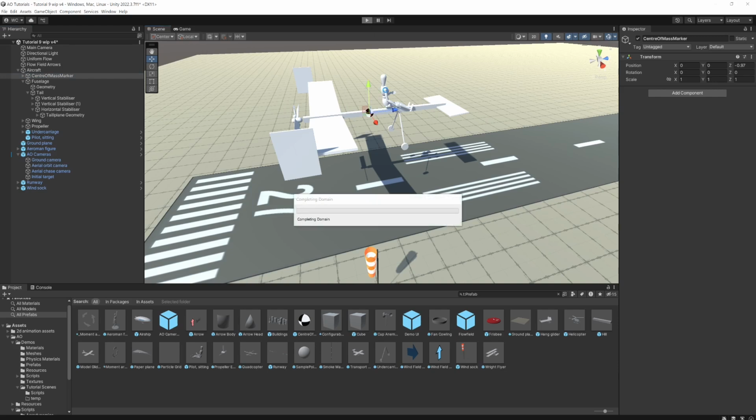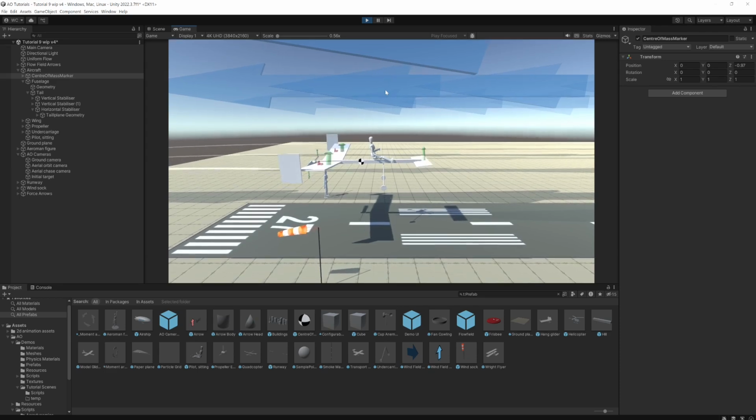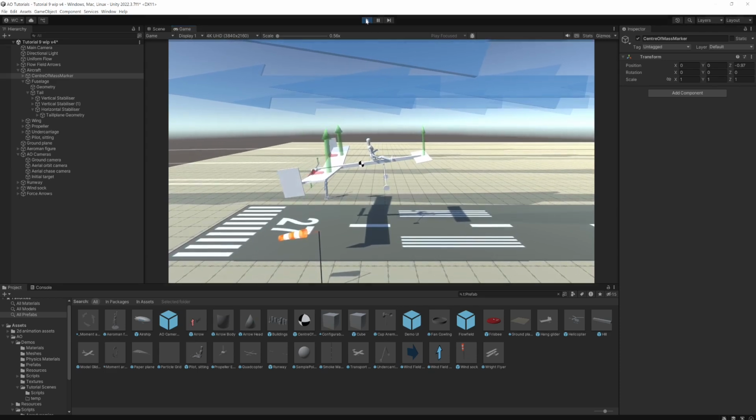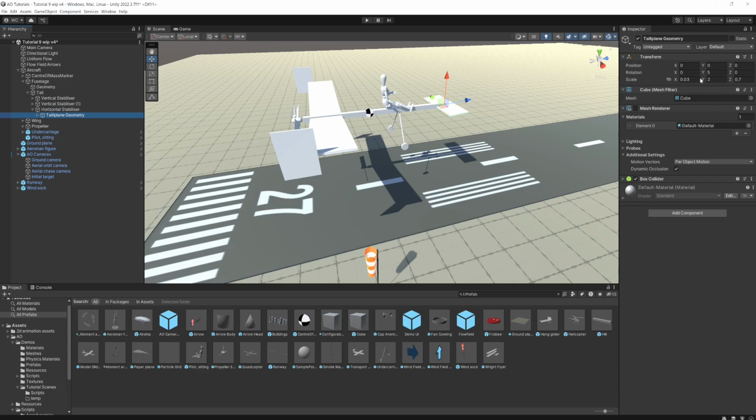So back there. Still trimming at a bit of a high incidence, so what I'm going to do just to make the trim at a slightly lower speed, I'm just going to knock that down to 3 degrees. So it doesn't sound much moving it by 2 degrees, but when you're configuring an aircraft, rigging it, a 3 degree setting between the wing and the tail, moving things a couple of degrees is quite significant.